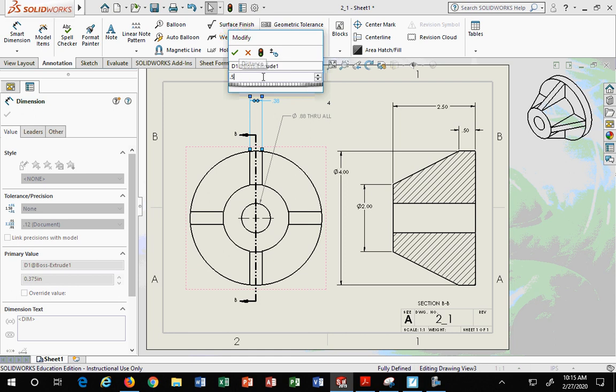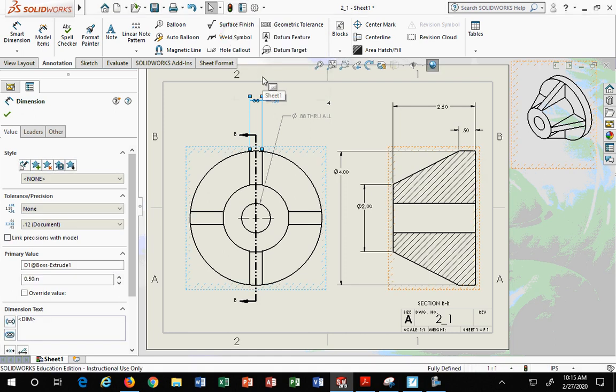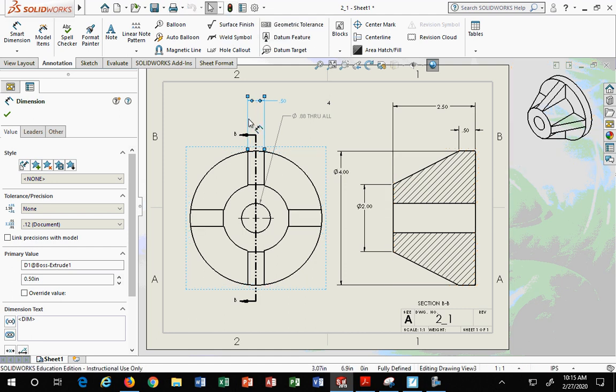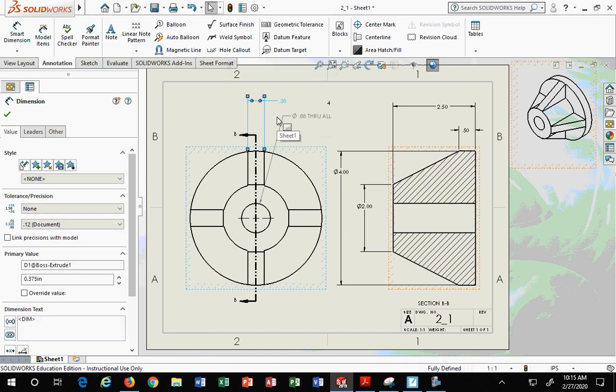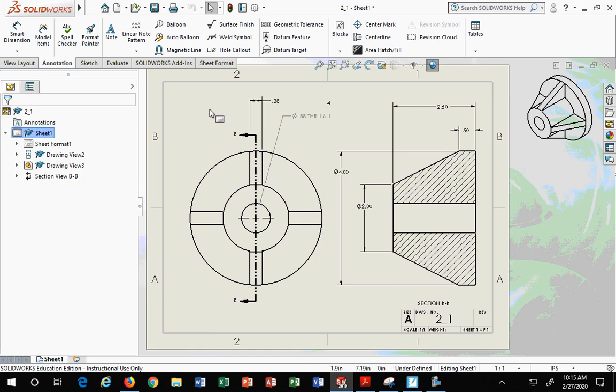So if I change this to 0.5 here, it wants to be updated. You see how it's got all these hatch lines everywhere. When I update it, it literally changes the width of each rib. And it changes it in the model, not just in the detail drawing. Use the power of the software. Do not strip it of its power by taking the model dimensions out. All right?